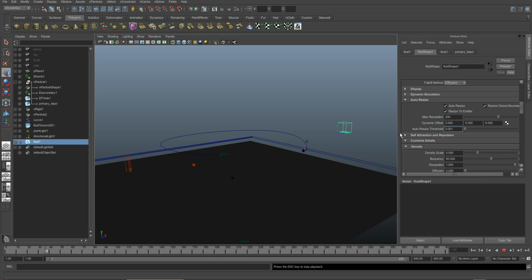and this sets the resize threshold of your fluid container. So I'll give you a better example. If I set the threshold to 1, you should see it clips the fluid a lot more. The fluid at this point basically needs to be very dense to make the container move. So the lower this is, the less dense your fluid needs to be. So as we're doing quite quick, in fact I'll leave this at 0.1,